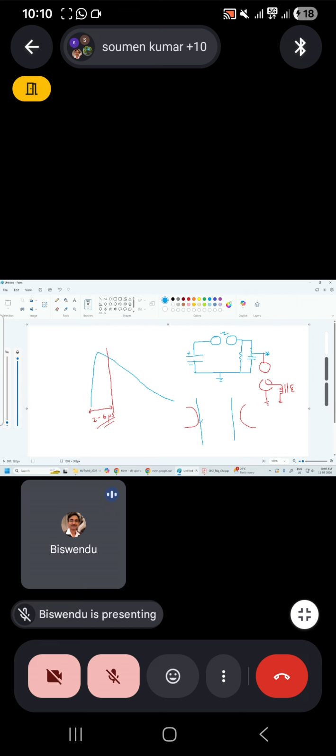If I divide this timeline as t1 and t2, t1 is the time to obtain the first electron, and the time to multiply is very short. So to reliably fire this chopped impulse, I need this initiating electron which is supplied by this transformer.